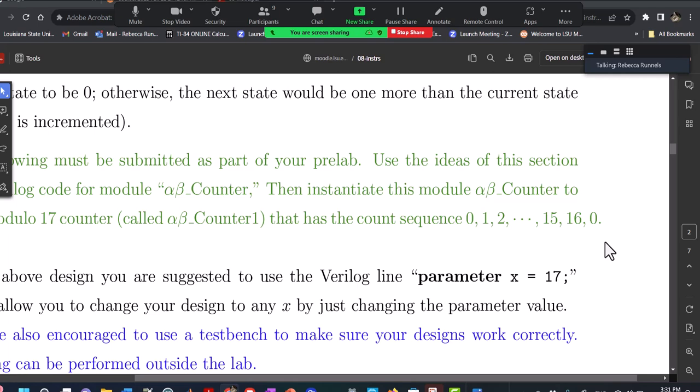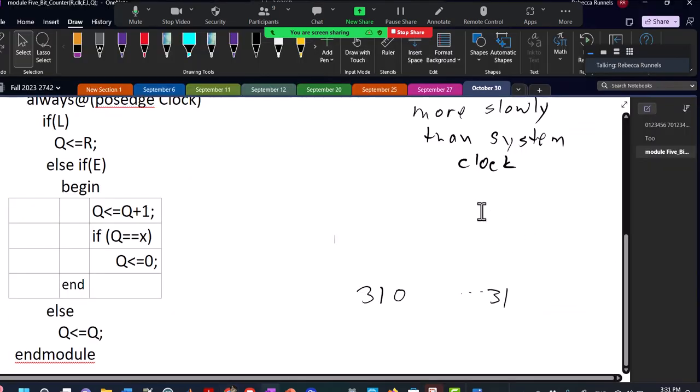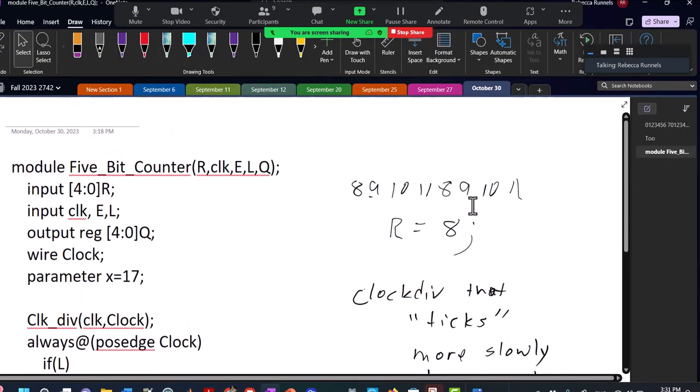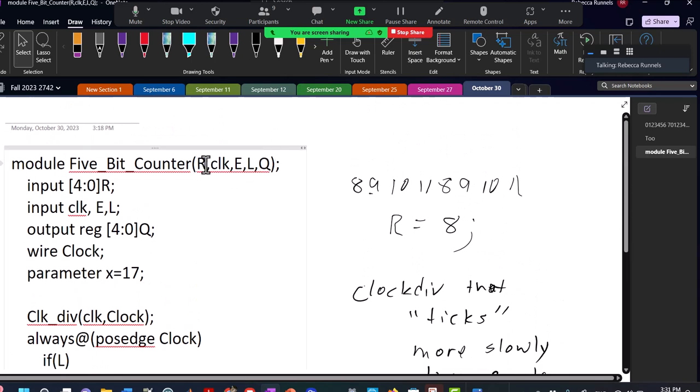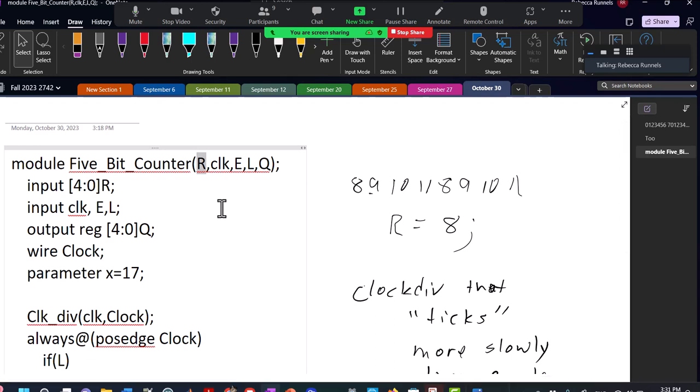The second number that you're talking about, that would be the load. That would be this R right here. And that's not a parameter. That would be something that you send it from another program. That could be a way of building the counter. It's not that having the two parameters would be wrong, because you might want to have a counter with a start value and an end value both as parameters.